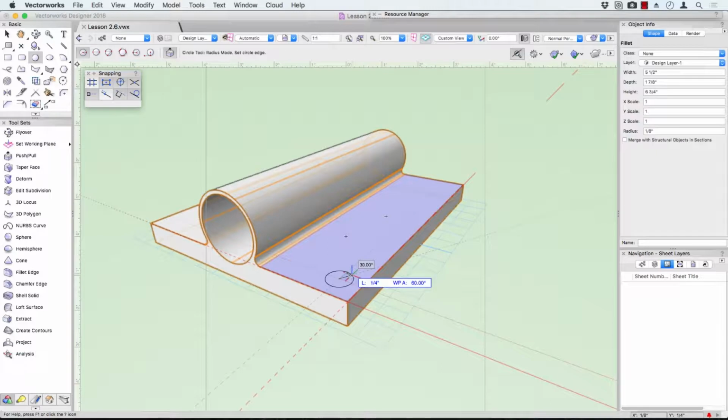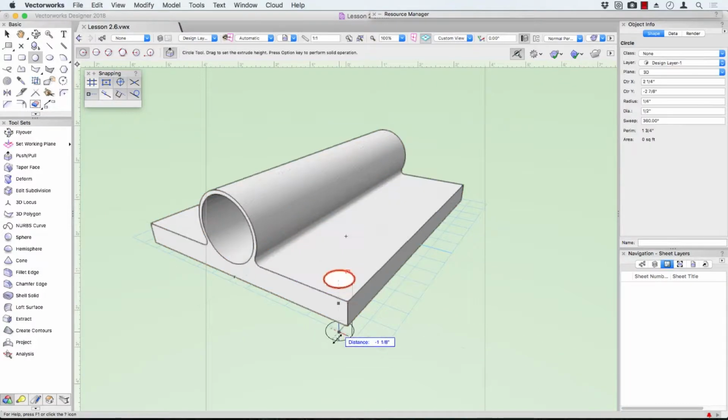This needs to be just over 1/4 of an inch. 7 millimeters would be a great size. What's that about? Let's put in 7 millimeters and see what happens. So 7 millimeters still says 1/4 of an inch. We'll use 1/4 of an inch for today. So click, remember to pull that through down here, and it's the Alt or the Option key, and click.